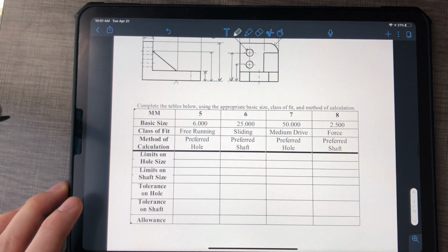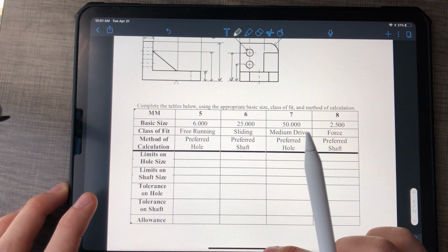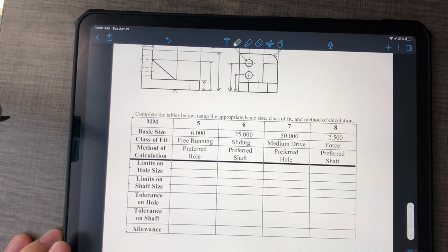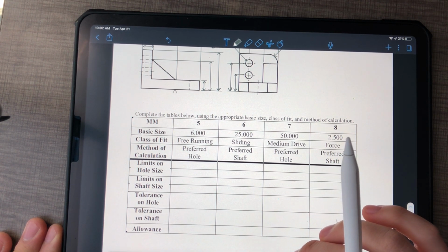Now for tolerances. Tolerances is basically a plug and chug from the textbook. So tolerances are the range of things that are allowed in a manufacturing process. For example, something from civil engineering, rebar. Rebar is sized a little bit differently. Each rebar has a number which corresponds to the amount of eighths of an inch that it is in diameter. And of course, you can say that something is a quarter of an inch, but when you make it, it's not going to be perfectly a quarter of an inch every time. That's what tolerances are. Tolerances are the range that results can come in when you make something.